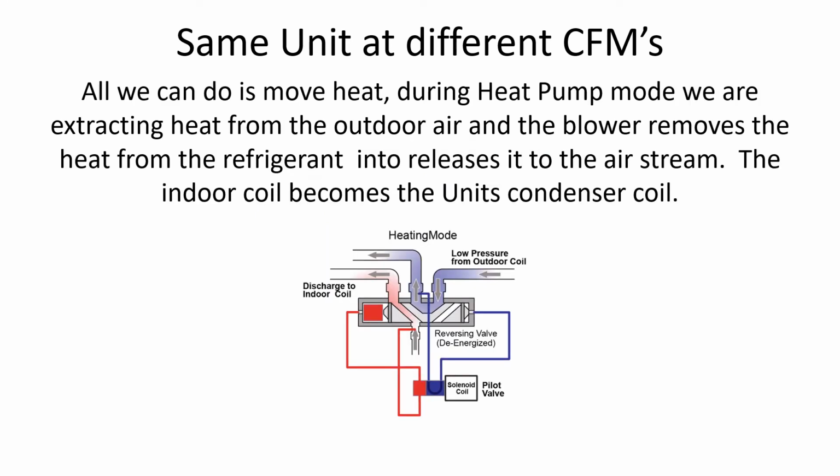So all we do is move heat. During the heat pump mode, we are extracting heat from the outdoor air, and the blower removes the heat, or extracts it from the refrigerant, and releases it in the airstream. The indoor coil becomes the unit's condensing coil.